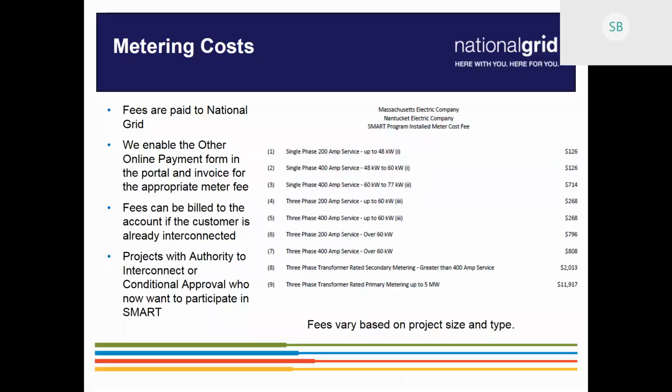provided with a revised nameplate. It doesn't have to be the stamped UL approved nameplate, but it has to be a labeling by the manufacturer of the derated amount for that inverter. And it has to be such that not just anybody can walk up and get into the system. Only an inverter manufacturer representative with the special passwords can get in to change that. So it has to be as secure and static as possible. As far as documentation within the study, we would look for some kind of written confirmation from the manufacturer that it has been securely derated down to that lower size. And then when we get to the witness test, we're going to look for that label on the unit itself.